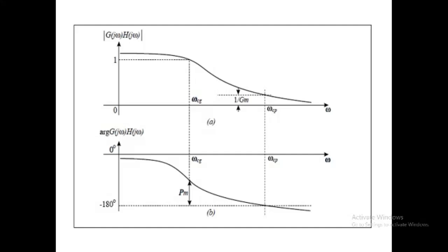So in this section we present the Bode diagram, which represents the magnitude and phase plot of the open loop frequency transfer function with respect to frequency, with magnitude calculated in decibels, that is dB. We will show how to read the values of Kp, Kv, and Ka.